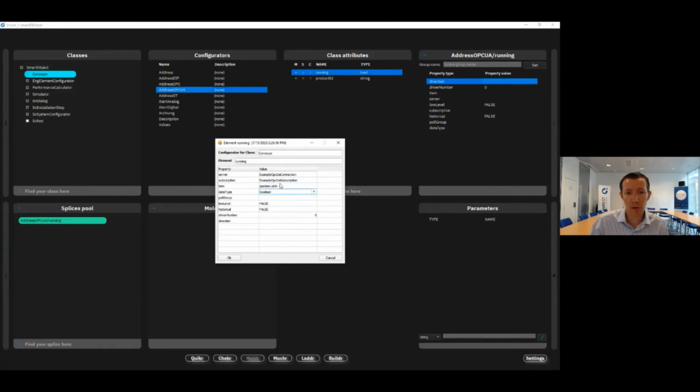We don't need polling because we're going to be subscribing to this data live. We can have some low-level smoothing. We can enable the history mode of Opc Ua. I'm just going to use driver number 1 to start with. And the direction I'm going to say is in and out, and it's going to be spontaneous because we're subscribing to this. Now, this is fine. This will work.